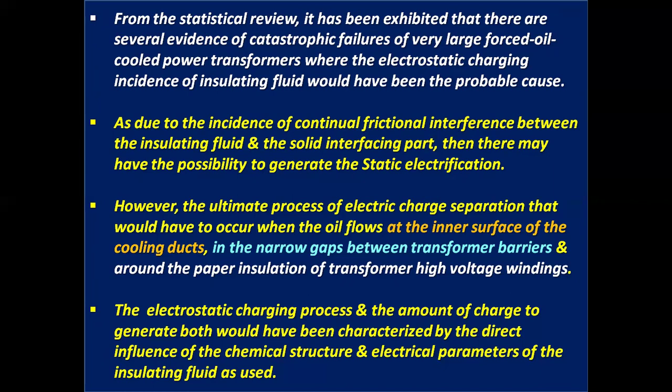However, the ultimate process of electric charge separation would occur when the oil flows at the inner surface of the cooling ducts in the narrow gaps between transformer barriers and around the paper insulation of transformer high voltage windings, HV windings.